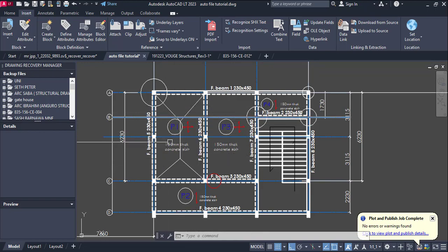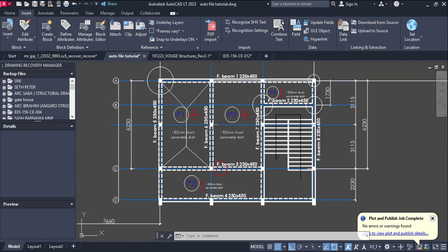But in a case where the panel is a square, everywhere is going to be triangle, triangle, triangle. So the whole loading is going to be triangular. The load from here is what is acting on this beam. The load here, entirely along this trapezium, is what is acting here. This is assumed to be the center. Then this triangle here, the entire load is going to be acting here.